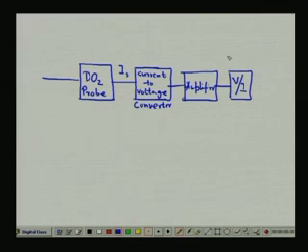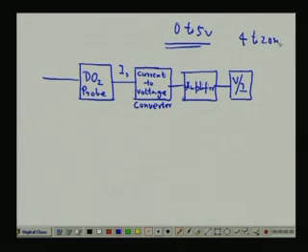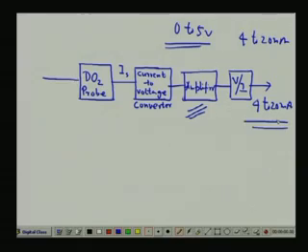Typically, converters are available for 0 to 5 volt, which will give you 4 to 20 milliampere. Okay. So, this can be done here itself, that means 0 to 5 volts will give you a current output of 4 to 20 milliampere, which is used for the measurements. As you know, in industry 4 to 20 milliampere is a standard. So, we will get it like this.